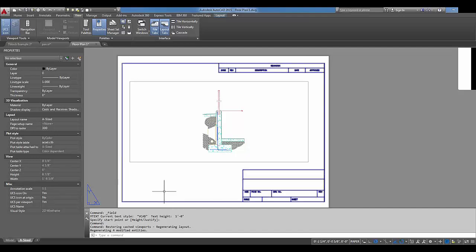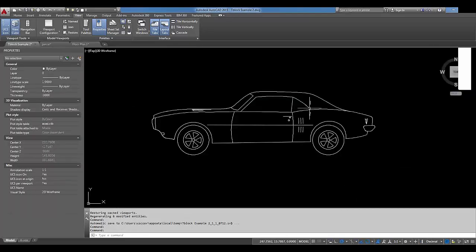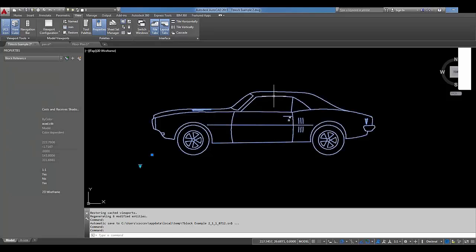One thing we get a lot of, and I'm going right back to Sean's car here, is: I'm working with visibility states in dynamic blocks, and can I apply attributes to those? And you can. This is obviously not a course on dynamic blocks, but we can work with dynamic blocks, attributes and fields at the same time.